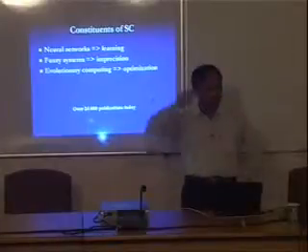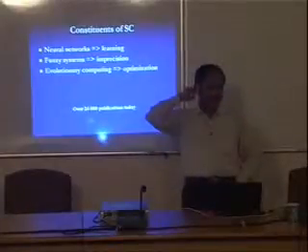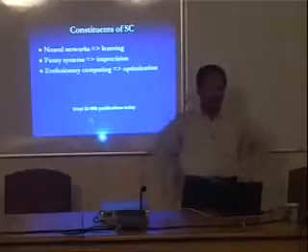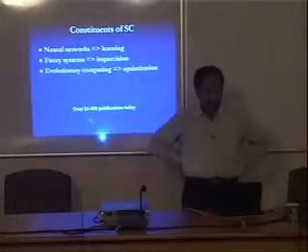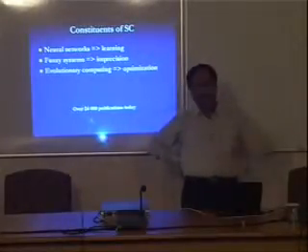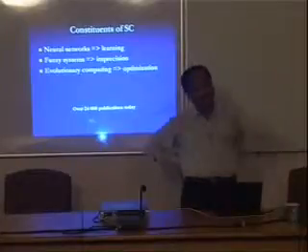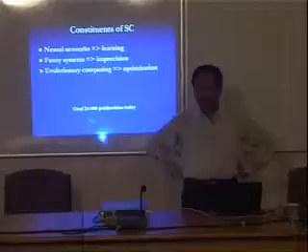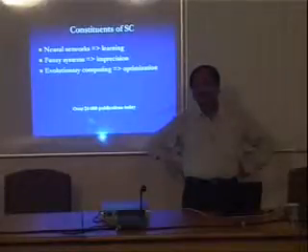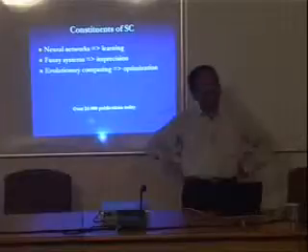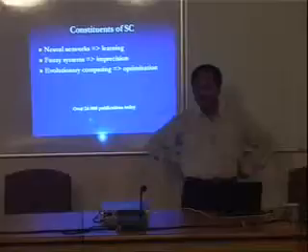Right? That you know. Can you give me an example where it can be used? For example, I am telling you, this fan, I want to design a controller for this fan. Right? So how will I go? I will first represent this fan in a state space model, x dot equal to ax plus bu.